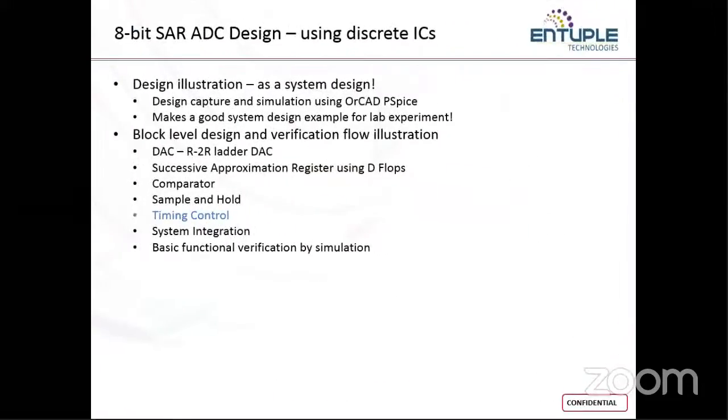Okay, so we are going to design this 8-bit SAR ADC using discrete ICs. And why do we go for discrete ICs? It is because in OrCAD PSpice we have all the blocks readily available. So we are going to design, capture, and simulate the design using OrCAD PSpice, which is also a good system design example for a lab experiment.